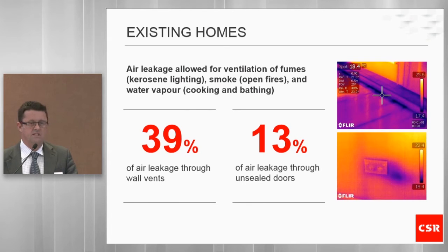The water vapour that is generated in a house through breathing, cooking, drying clothes inside in cool climates, which is a common thing that we do, that vapour's got to be dealt with somehow. Jesse's going to handle a lot of that later on, but it's very critical. It's critical because the National Research Council here has suggested that about 90% of our time is now spent indoors. The gaps in houses, historically, about 39% of the air leakage was through the wall vents, and 13% was through around unsealed doors.